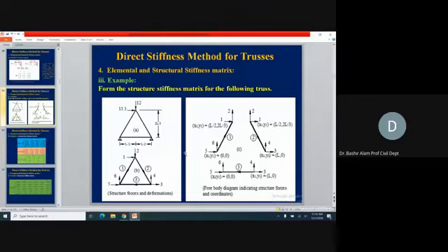Now, example, here an actual truss is given. At the truss top, we have loads of 11.5 and 12, and you can see the distances are L by 2, L by 2, and 2L by 3. These are defining the nodes. So this is example 1. Here at this top location, we have these displacements. I would like to have this 2 also in the upward direction. So rightward and upward we take positive. So you just reverse the direction of this 2.